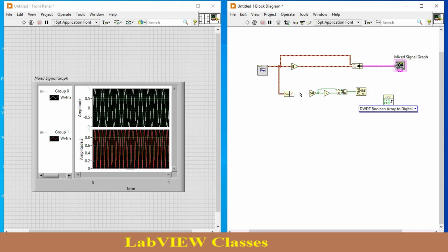When over here we have the scalar value that is in floating value, like 2.0, not 2, it is because the sine wave is between 1 and -1. So over here I got the value in floating value. Then according to the comparator, I just got the value true and false only. So over here we have Boolean values. Now I just convert this value into the digital waveform, and this digital waveform goes to my bundle function.